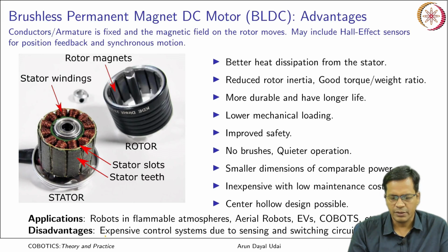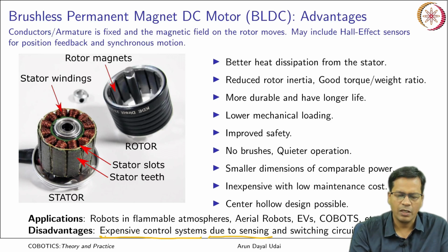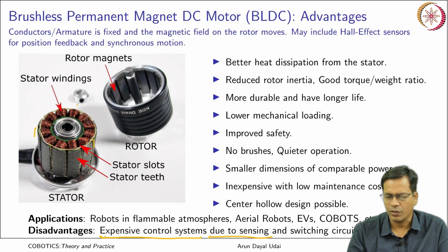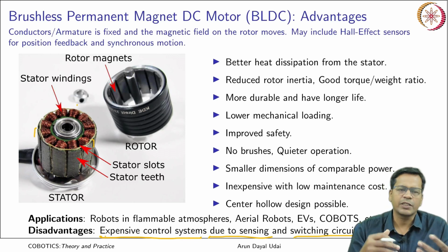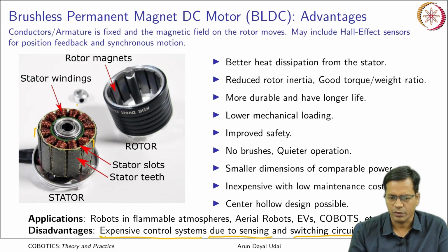The disadvantage is only one: they are expensive because of the control system, the kind of winding, and the kind of sensing, with Hall effect sensors at 3 places. The switching circuitry is a little bit complex because of the 3-phase winding. We will discuss in detail. So these arrangements cause a little higher cost for these motors.